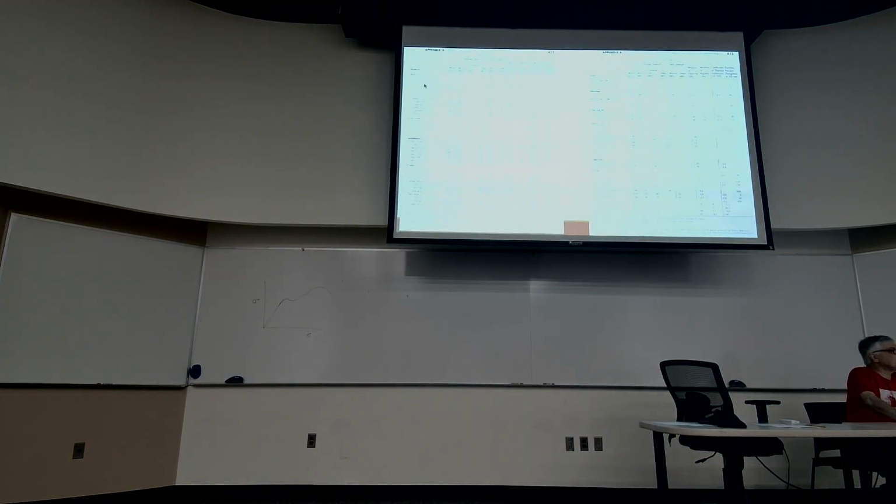So if you take steel, for example, you can see that ultimate strength sigma U is 400 megapascal for this first one listed here. And if you look at this table, we have 58 KSI. So that means 58,000 PSI, that's sigma U.